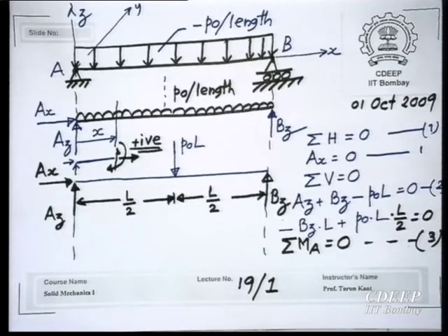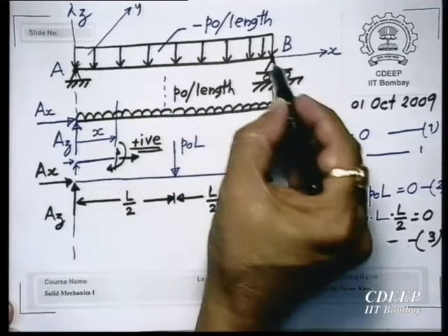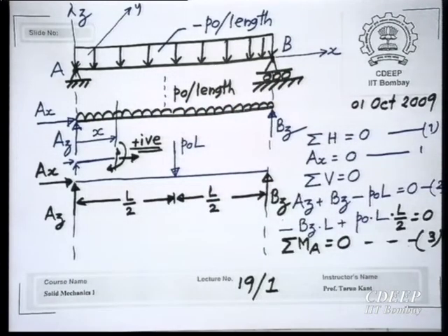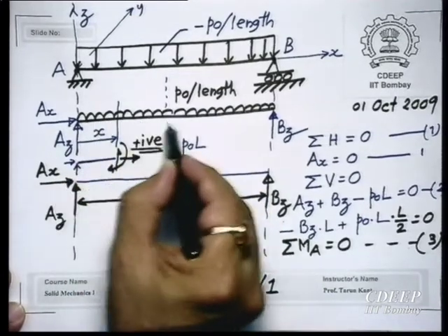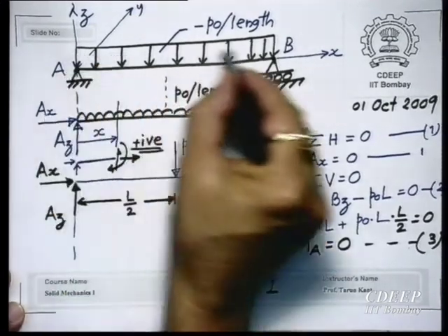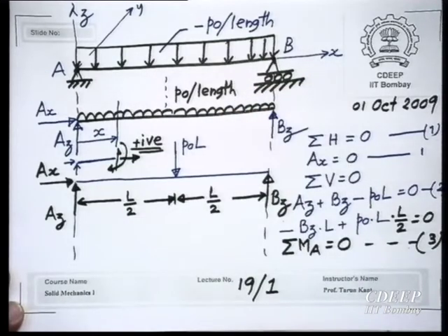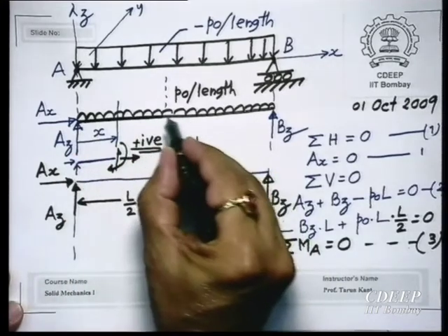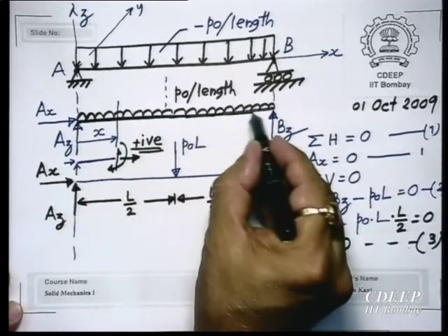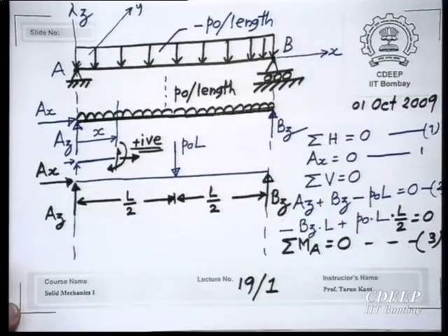So, I have drawn this. See, because loads are always put on the member, they will always be downwards. So, what I am saying, do not think of load that is acting upwards. It is also shown like this. Instead of showing it like this, UDL, uniformly distributed load, you can show it by this. So, you have the beam shown by its centroidal axis, a single line, and then this is the loading acting on it.